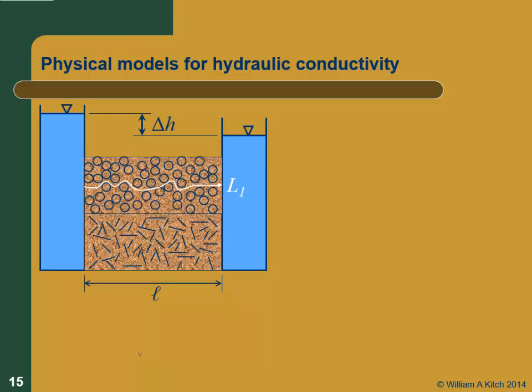But there's a theory that discusses that, and that's, I would say, Darcy-Weisbach, the Kozeny-Carman. So let's look at what's really going on. In this case, I've turned my permeameter on its side just to draw things, and if I'm a molecule of water here, I'm actually going to be traveling, not straight across the permeameter, and my travel distance is going to be what I'm going to call big L1, and it's going to be longer than just the distance L, which is the length of the gross flow path, right?